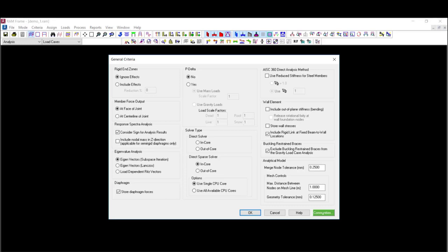However, the Ritz analysis can cut this problem short. This method generally captures all the modes having significantly high mass participation factors, and thus you will end up reaching the 90% target with a fewer number of modes. Other advantages of this Ritz analysis are that the Ritz vector solution is faster and requires less memory than the traditional eigen solution method. And Ritz vector automatically considers all the residual modes of the structure, so you don't have to do the missing mass consideration after you do the traditional analysis.